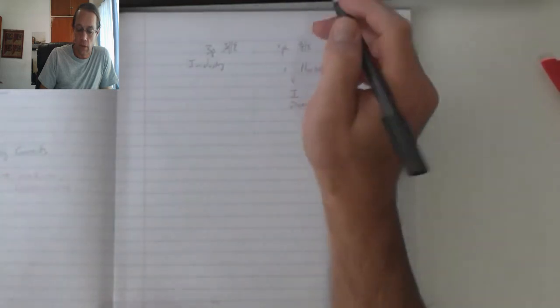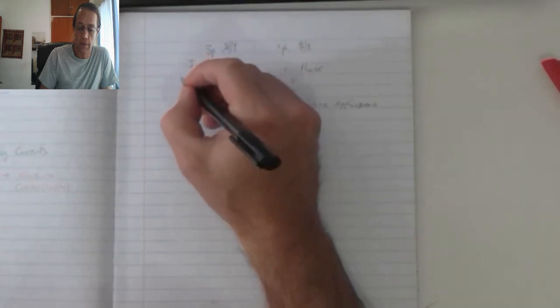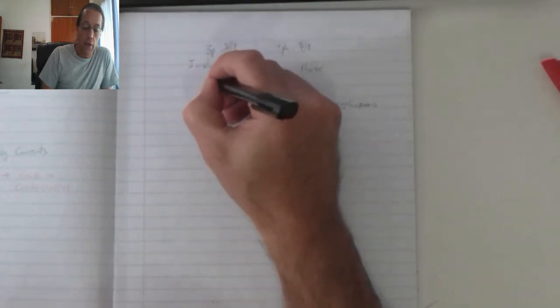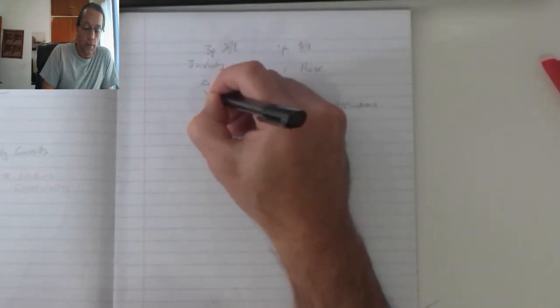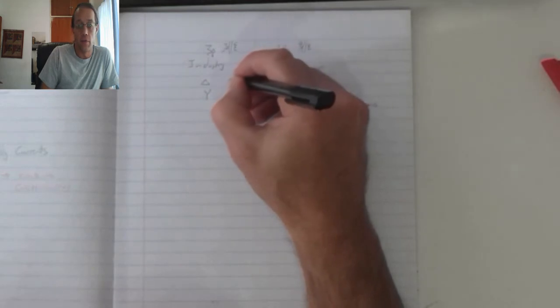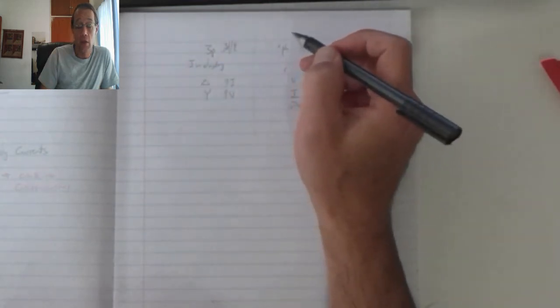Okay, now as we saw with the star and delta calculations with generators, depending on what we need, we can connect this into a delta configuration or a star configuration, depending on what we need, high current or high voltage, due to the line versus phase values.